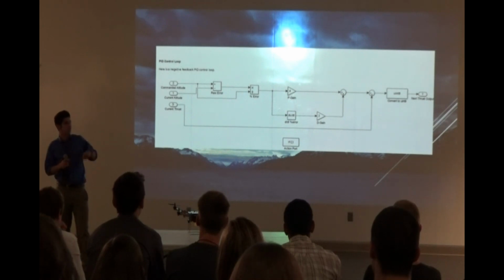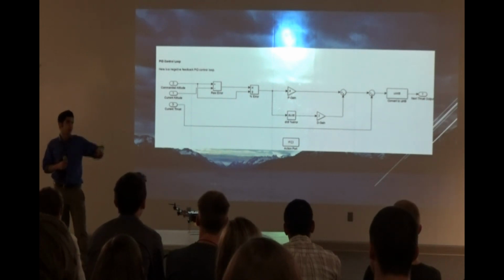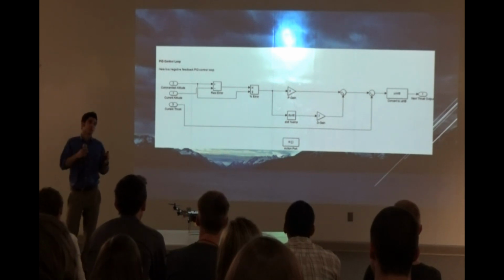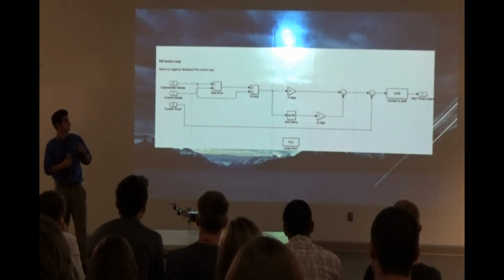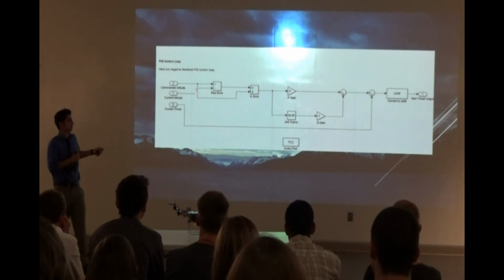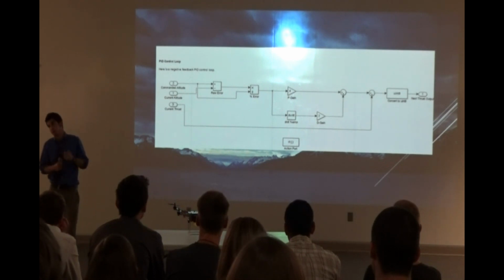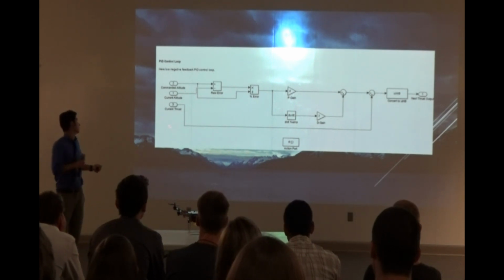So it would be facing like a wall over there, like down, and then possibly forward. And so now, if we can control our position on each axis, then theoretically we can hold it still in space. And so the idea is we have a commanded altitude, so what the user would set where the quad needs to be, and we have the current altitude being measured by the sensors.